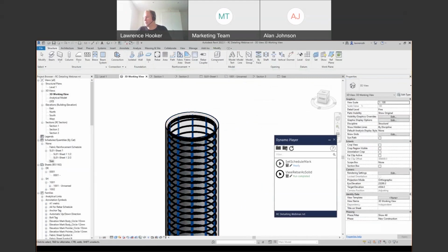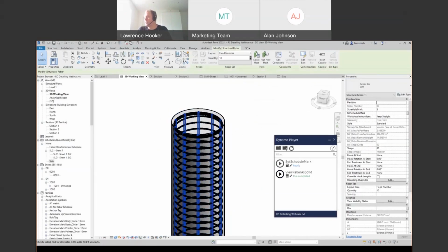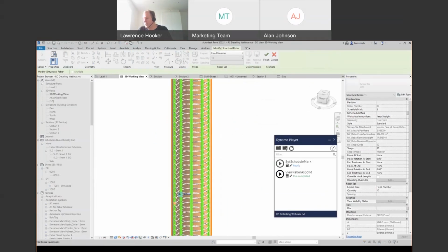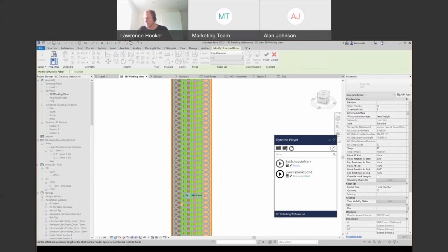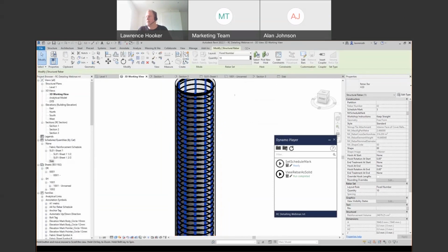Once again, I want to see those as solid, so I can just run that again. There they are. Obviously, I'll need to constrain those, so I can use rebar constraints just to make sure that they are inboard of the links in there. So if I go down in here, let's say that that's going to be -14. Oops, -14, not 143. Okay, and there it is. And there's our rebar placed in.